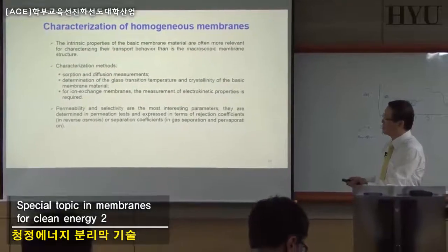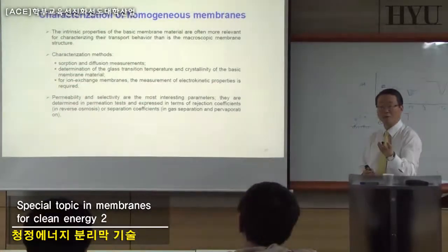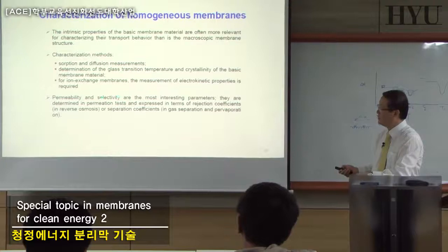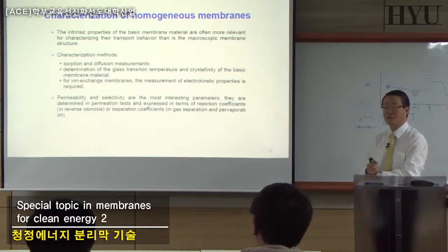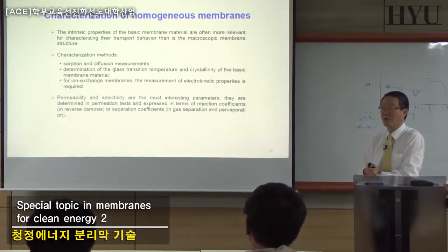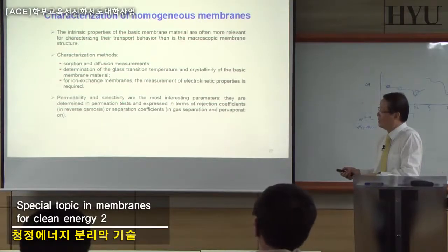And in this case, permeability, hydraulic permeability or gas permeability, or selectivity. I'll tell you the difference between selectivity and separation factor, but selectivity and permeability are the intrinsic properties of the membrane. This is an interesting parameter, the same as in reverse osmosis.